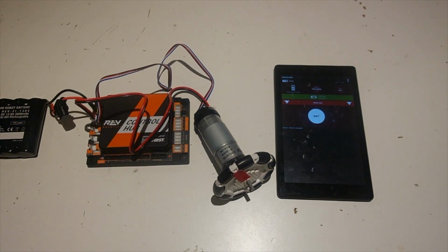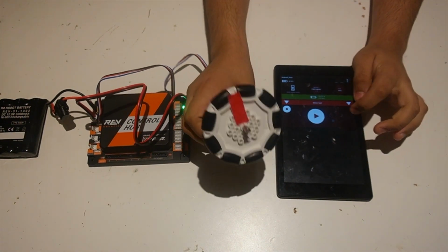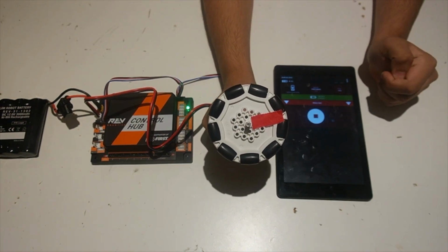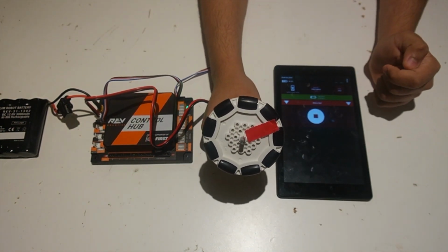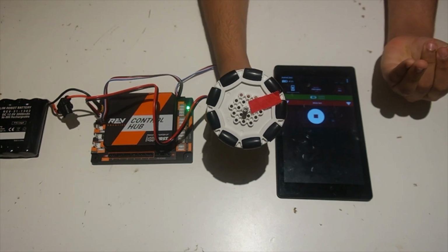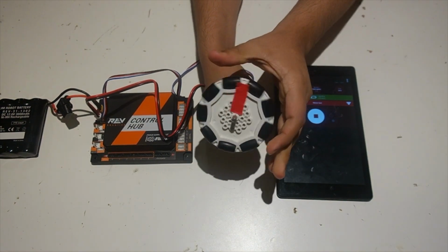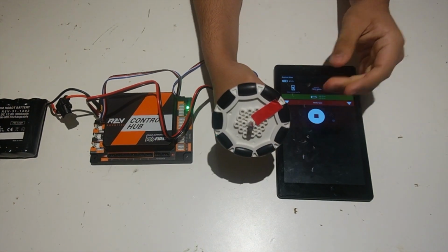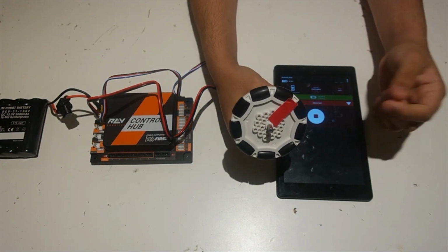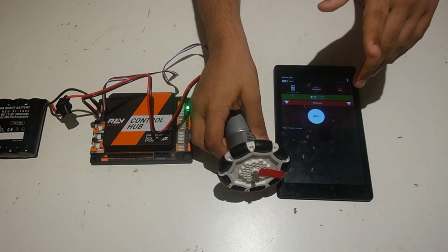Now I have my motor test. I'm going to select it and hit init, and you can see when I hit play, it goes at full speed because I set the power to 1, until it overshoots a little bit, and it comes back. And now you can see whenever I try to move it, it always tries to correct, which is great because this is perfect for an arm or your drivetrain to keep it in place. So that's what run to position does.